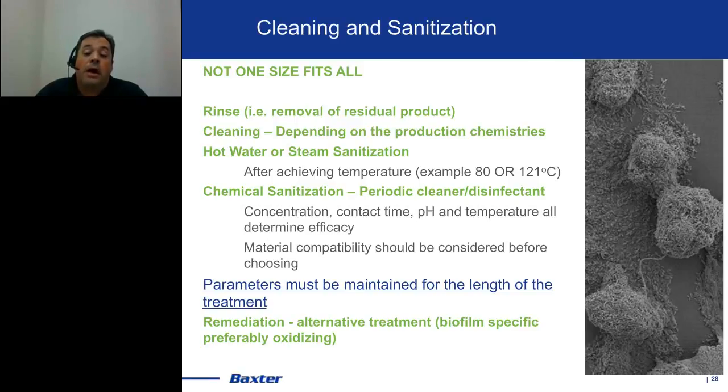And when I say that, that would mean, for example, if your hot water is entering a system at 80 degrees C for sanitization, but over the process of your whole system, it's cooling down such that when it comes out, it's at room temperature, there's probably a significant portion of your system that's not receiving any treatment. So it needs to be at an effective temperature, or if it's chemistry, concentration, throughout that entire length and over the entire time frame. So if you've got a 30-minute treatment, it needs to be effective over that entire time frame.